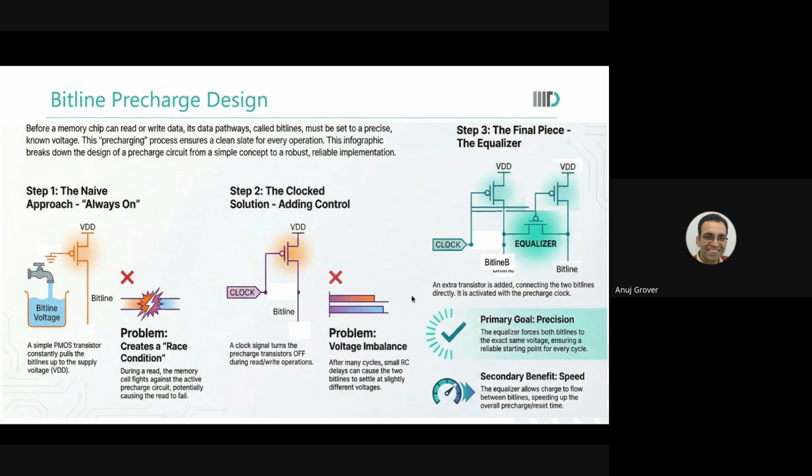Suppose I say that I want the bit lines to converge to 2 millivolts of each other. What is the consequence? One will discharge early, one will discharge later. No. I just said that the equalizer will bring them to almost equal level, not exactly equal level. If that almost is equal to 2 millivolts, what is the consequence?